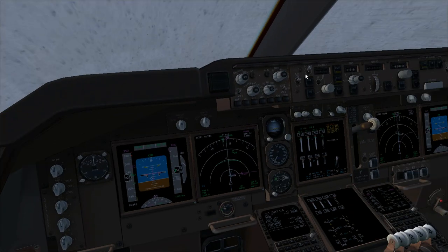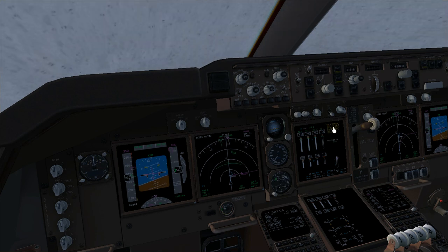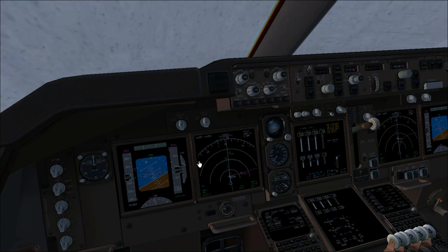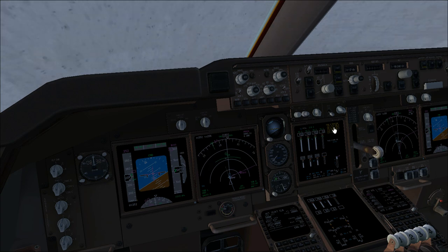We go to the main panel. Engine fire is now out and we are engine 4 shut down. Flaps up please, and flaps up selecting, and we can set gear off. At this moment we have finished the procedure for the emergency.